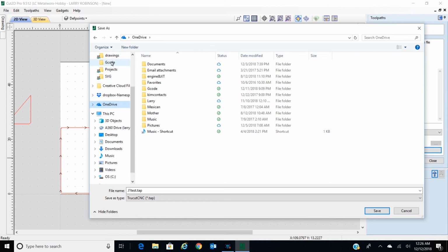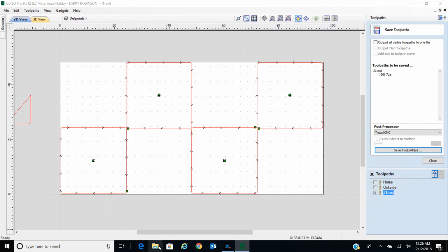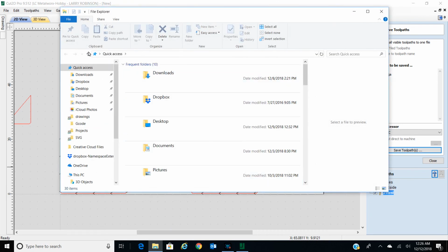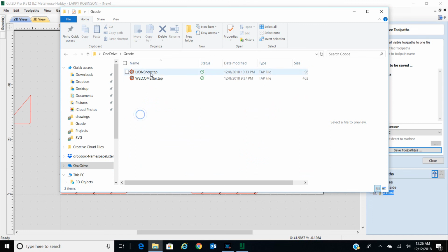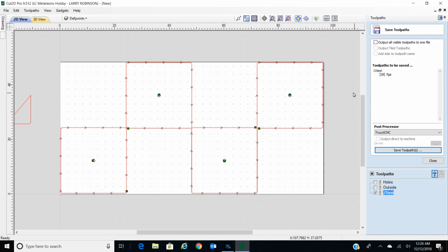So when I get out to the machine out there, it needs to be in the G-code folder that's on your computer, on your plasma table. So when I go out there to the machine, all I do is open the File Explorer folder here. Now, all I do is find that file, this is where I put them right here, and I just drag this into the G-code folder that's on your desktop, on your plasma table, and then just close everything. When you get ready to run, you open Mach 4, and then you just load your G-code file that you just moved into there. That works for me. I mean, some guys probably put it on a little thumb drive or whatever. It doesn't matter as long as you get that file and load it in Mach 4.